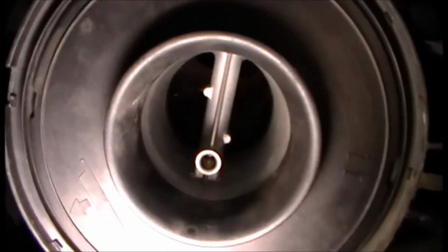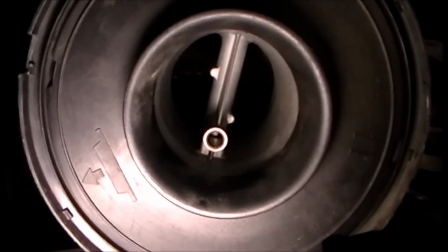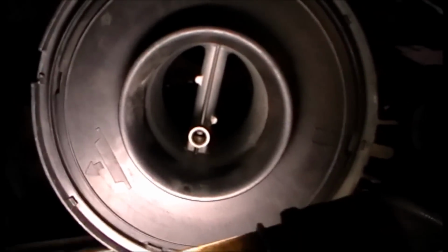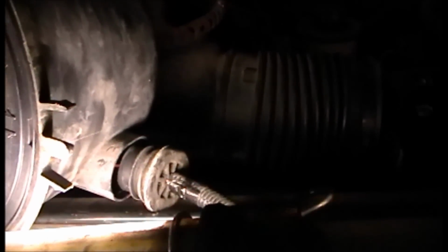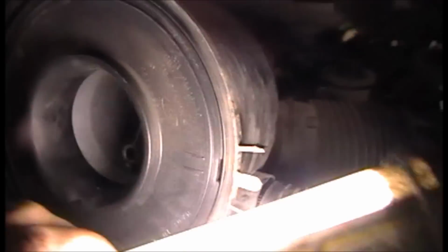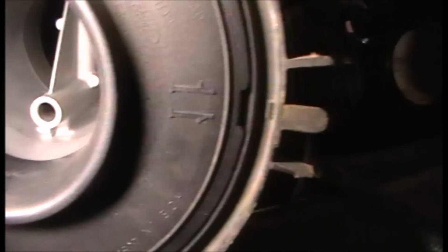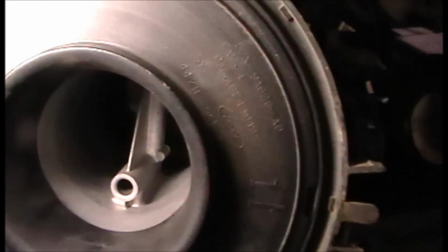If you look at the inside, there's the mass airflow sensor, and the little hole there is where the metered air goes through to measure where the hot wire and cold wire are. And you have a grommet over here, so you peel the grommet back, and you can get to the connector. And there are marks on the actual insides right there that'll line up, so you have the orientation right when you put it back together.